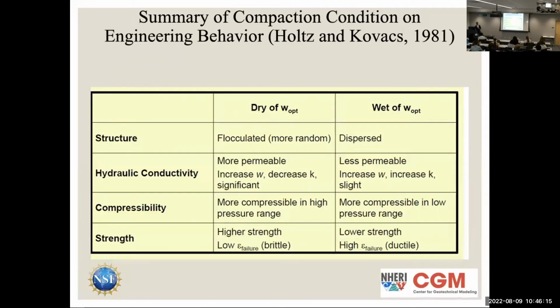Another thing we focused on is the dry of optimum and the wet of optimum, as I explained in the introductory slide. We wanted to use dry of optimum because, in order to build the levee further on, we want to induce a crack in it to see if our idea actually worked. If it's more wet of optimum and you want to induce a crack, that's not going to work. You're not going to see a crack. In the end it's just going to be a pile of mud. Can't really work with it.